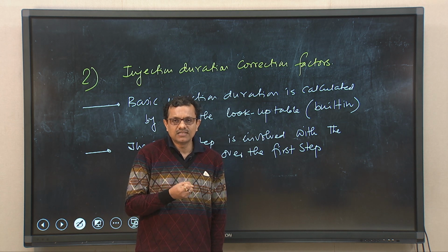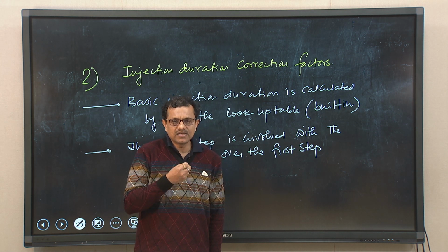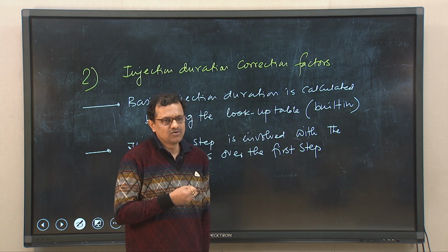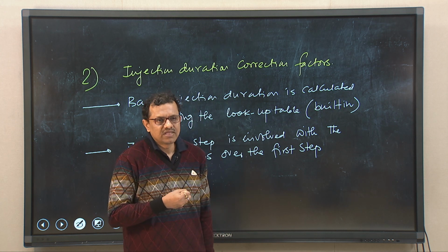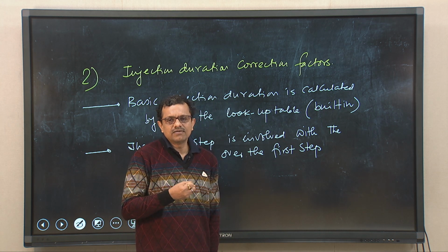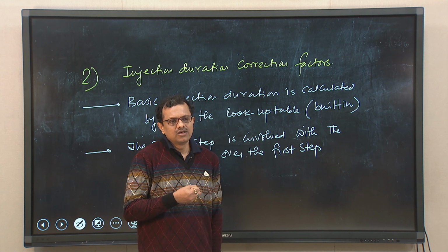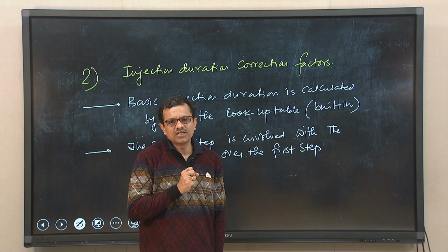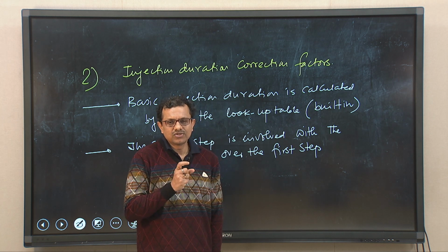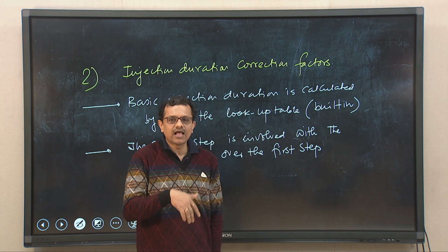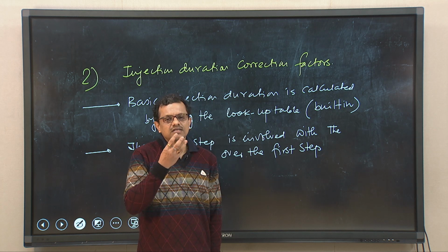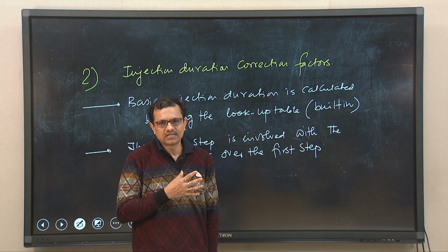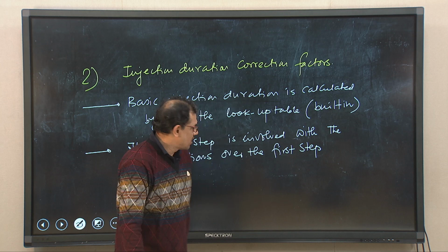If we need to run the engine always at the best efficiency, and ensure that the emission level is under control or reduced, we always need some correction over the basic injection duration, and those corrections are again reliant on the signals from a few input sensors.